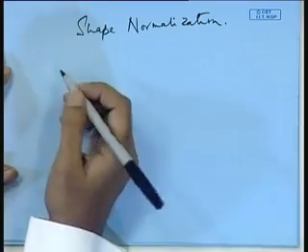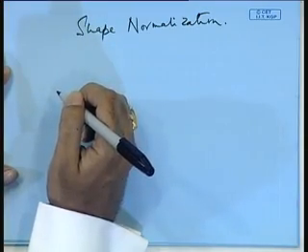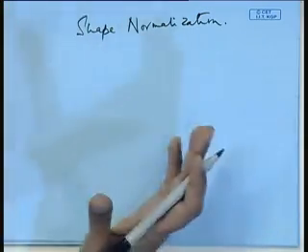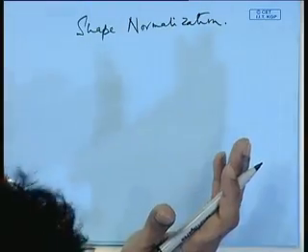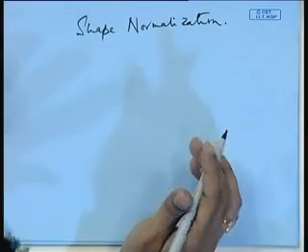So, shape normalization is essentially that if you have any shape, be it spherical, be it cylindrical, be it some very weird shape, you know, the pentagon or some kind of weird pyramidal shape, which you cannot capture, you cannot solve the equation in every shape. So, what you do is you transform these shapes into standard shapes, for example, a slab, and then you do all the calculations.